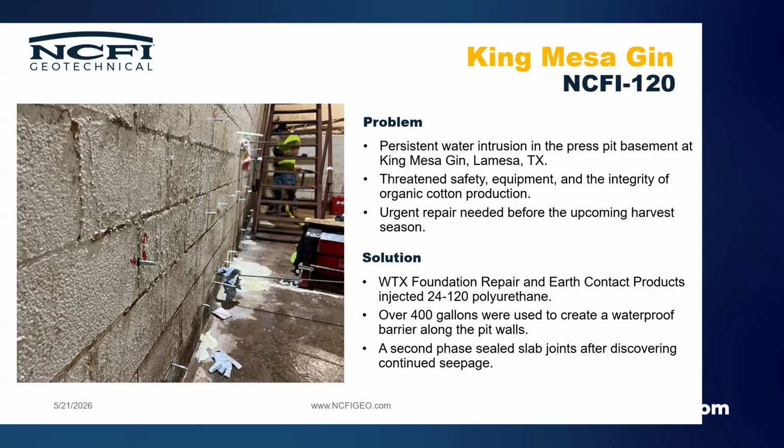If it is a sandy soil, then it is going to permeate that and create a grout curtain on the outside of that structure to keep the water out. This particular one took over 400 gallons of material and stopped all the water from getting in.